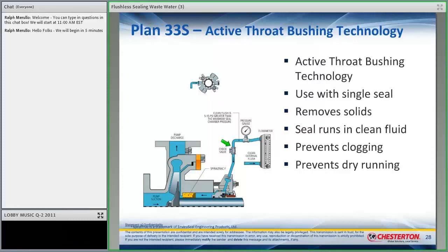Now, the bad news with this is when the pump shuts down, the flush will flow, right? So you would want to use this in a situation where the pump is always running, right? Okay. So then hydraulically, if the pump is running at low pressure, you're covered, right? Perfect. However, if the pump starts and stops and starts and stops, you probably want to use a solenoid valve instead, a valve that will run flush just at start and just at shutdown. Okay. So that's where you use the two different approaches, okay? Perfect.